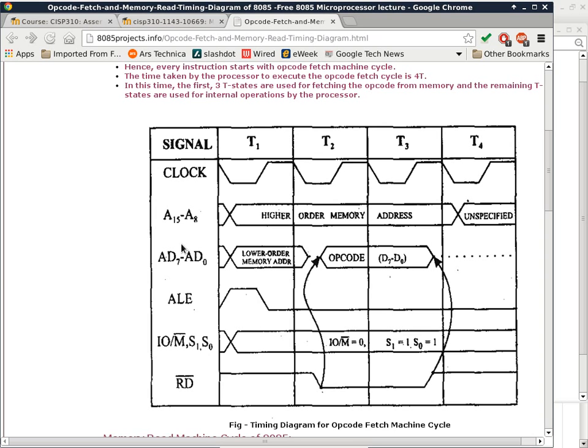So anyway, getting back to this discussion here, if you look up a current circuit board, can anyone kind of guess how many layers these circuit boards have? 6 layers. Okay, 6-layer circuit board. Now, what do we mean by 6-layer circuit board? You look at the edge of the circuit board, you basically find that there's one copper layer at the top, one copper layer at the bottom. This is a double-sided or 2-layer circuit board, which is pretty inexpensive to manufacture, no problem. This is a 3-layer circuit board, 4, 5, 6-layer circuit board.